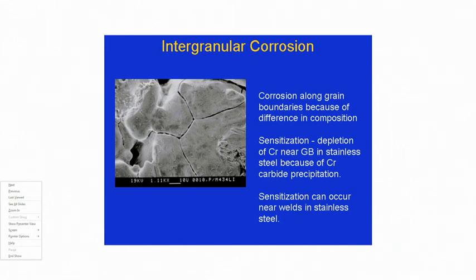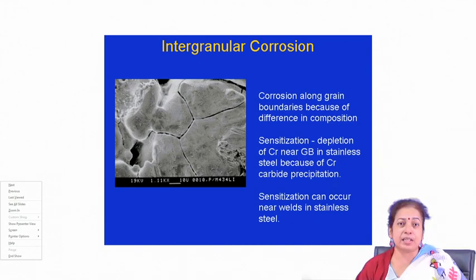But if we move in the nanometer direction, and look at the corrosion rate of nanostructured materials, you will find that instead of increasing, the corrosion rate is even lower than that of the annealed, coarse grained microstructure. This is a little different effect, because there also grain boundaries are attacked at a slightly higher rate than grains, and hence grain boundaries are significant in the corrosion behavior.